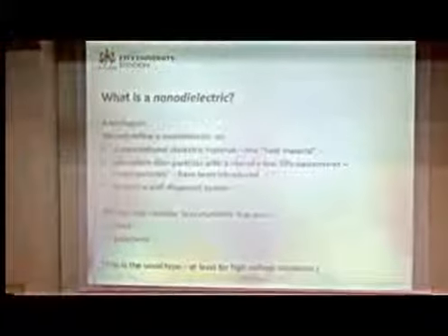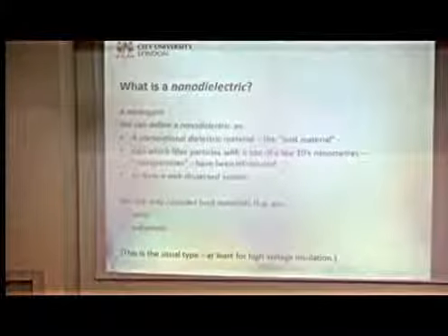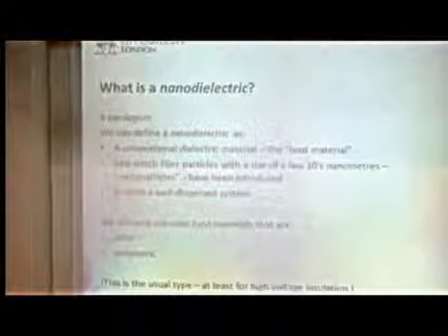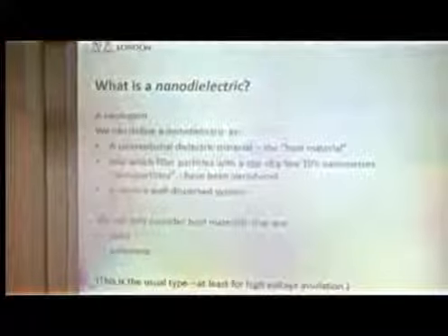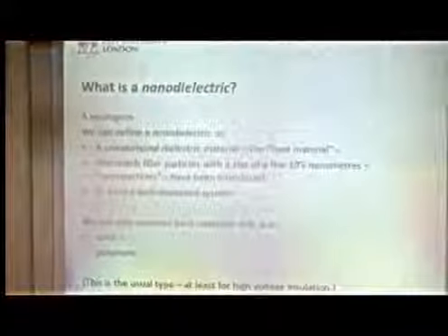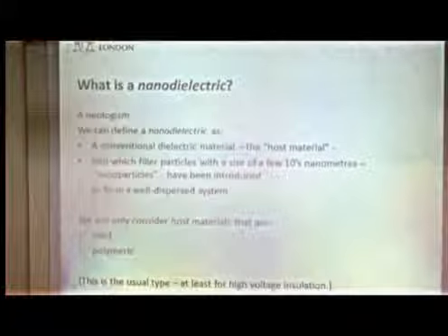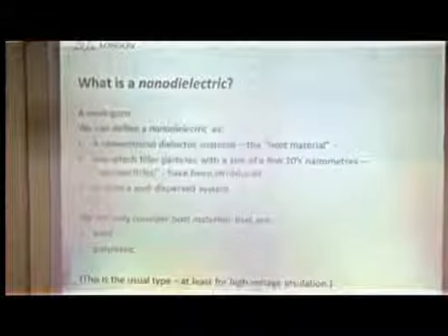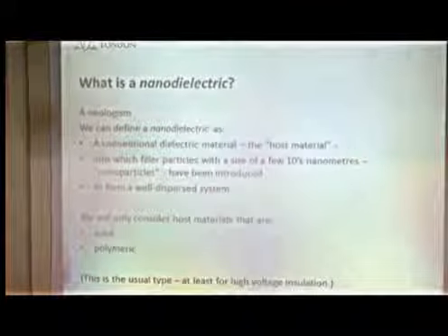But we could define a nanodielectric typically as a conventional dielectric material, often a polymer, though it could be other materials, which I'll refer to as the host during this afternoon, into which we've put some filler particles with a size of perhaps a few tens of nanometers, perhaps a bit less than that.